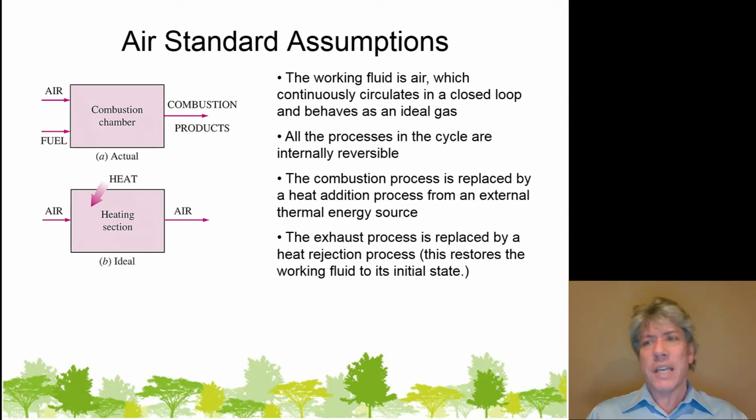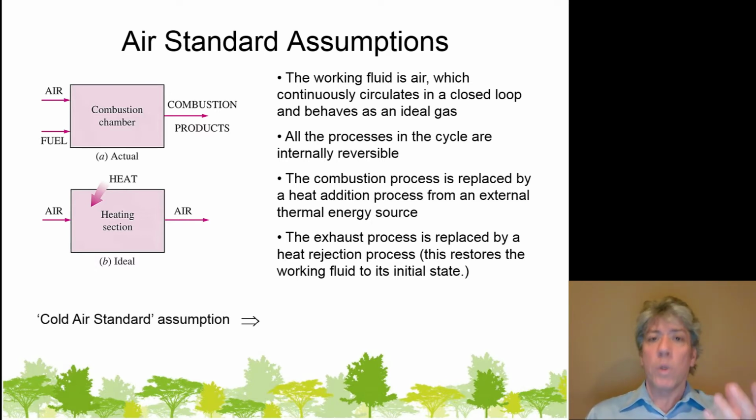And all we're really saying is that, for example, in a piston cylinder device, the compression process has no friction and that it's reversible and that there's no heat transfer during it. And that's not such a bad assumption, because that would give us the maximum amount of work output from the power cycle, for example. The combustion process, as I said, is replaced by a heat addition process, since that's really the purpose of the fuel.